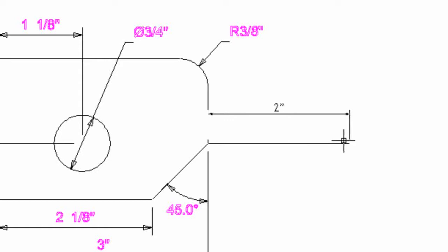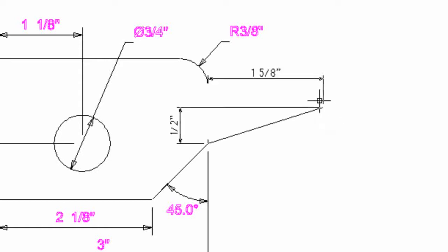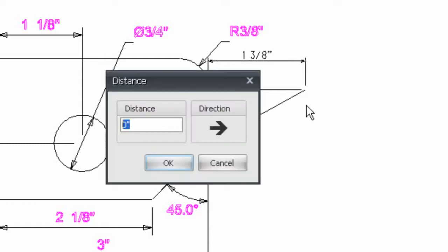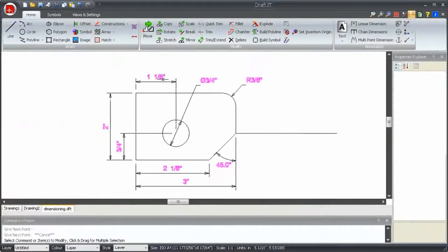Now, let's look at how we input fractional inches. As we are drawing a line, let's press an arrow key, say the right arrow, to go to an input box. You will see that the distance is set to 0 inches. Let's say we want the line to be 3 inches long. It's easy. We can just type 3 and press enter or click OK. You may or may not have noticed the quote mark which was added as we accepted the value. So the line is now drawn 3 inches long.